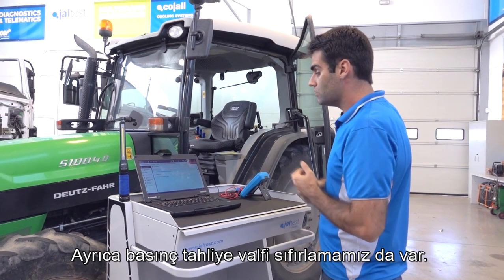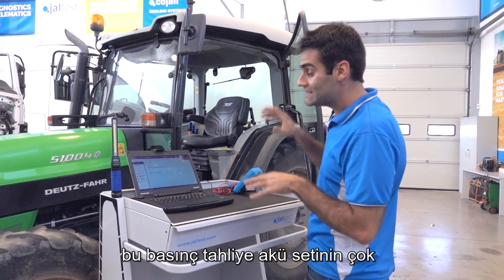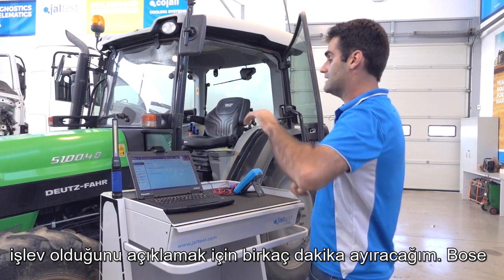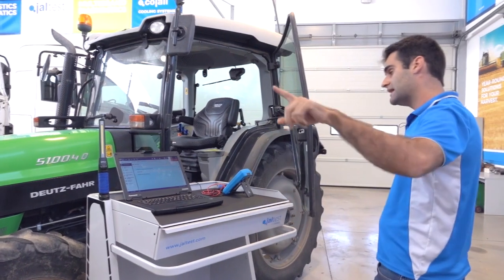And then we've got also the pressure relief valve reset. I will take a couple of minutes, guys, to explain to you that this pressure relief valve reset is such an important function. It's very common in the Bosch injection systems to find this pressure relief valve in the injector rail.